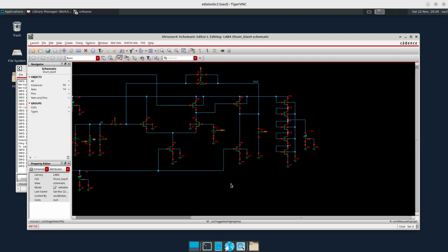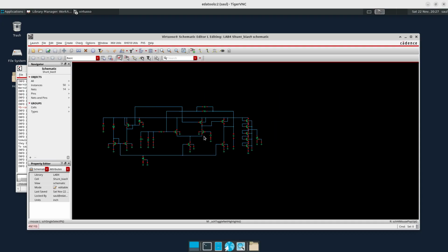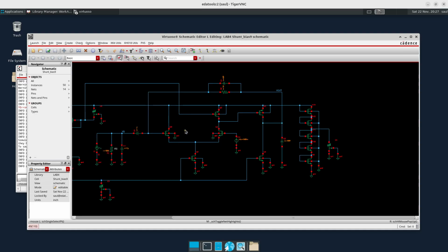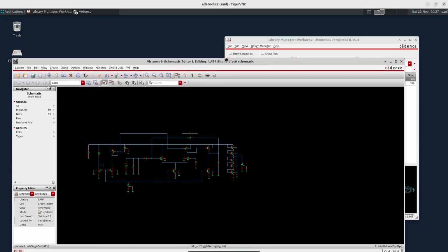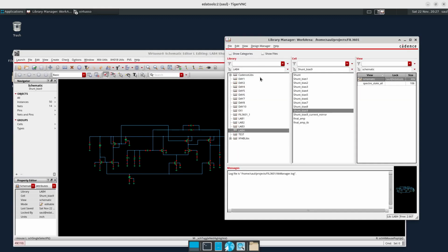It is basically that any variation in the power supply will immediately be seen in the voltage reference, which means that it has a really poor power supply rejection ratio. So even small variations on the power supply here will change this voltage reference. So it might have an impact on the performance of the circuit if it is sensitive to that. So we're going to do some simulations of this so we can take a look at what the impact of the power supply is. So this is one of the options. We have actually another alternative.